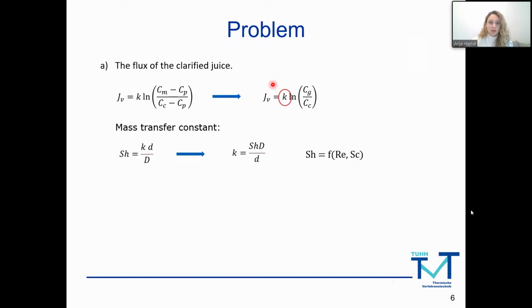Somebody is asking, when using asymmetric membranes, should the smallest pore size face upstream or downstream? I imagine you mean here the feed or the permeate side, so I will answer accordingly. Yes, it should be on the feed side, and then you have the support towards the permeate side.